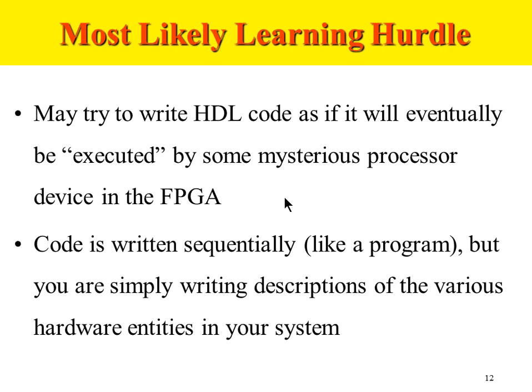But HDL language is not a software programming language. A software programming language works sequentially. Let's take a C program, because you might have done embedded C programs. Whether your C program is very small, 10 or 20 lines, or very long, thousands of lines, it doesn't matter how long or short your program is, it will always execute sequentially, first line to last line.